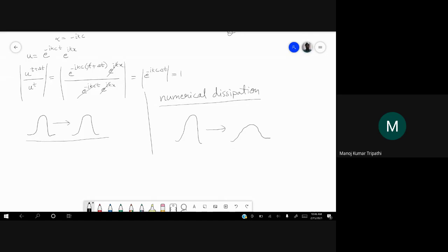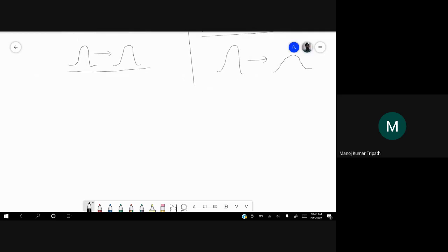So similarly, let's say you are solving Navier-Stokes equations and you want to solve for inviscid flow where there is no viscosity, and you set viscosity equal to 0. Let me write the Navier-Stokes equation here. Density multiplied by (dou u by dou t plus u dot del u) equals minus del p plus mu del square u. This is the equation without any gravity and other force terms.